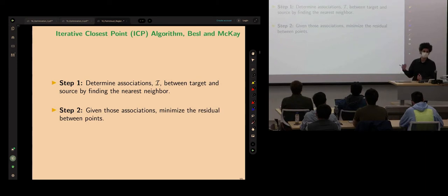Unless every single registration you do is perfect, which is impossible in practice, it will be an odometry and needs to be combined with other techniques in the context of SLAM. But because we might get odometry out of it, you could classify it in the localization category. The point clouds are given as measurements.